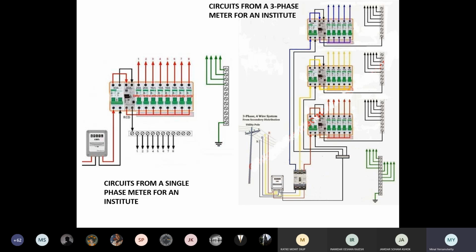This happens in the old houses, huh? So don't take this as an example. This is happening in the old houses which are going for redevelopment or need to go for redevelopment. So suppose something like that happened. The second protection point is the fuse near the meter. So for the whole line going down, the second control point is your meter. And once the meter clocks out, then the cutout is there. That is the strongest of the lot because it is taking care of the entire load and more.